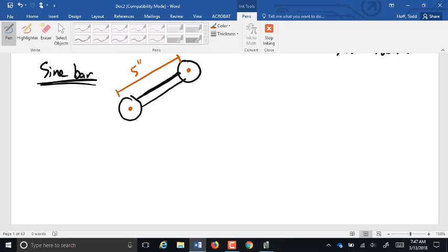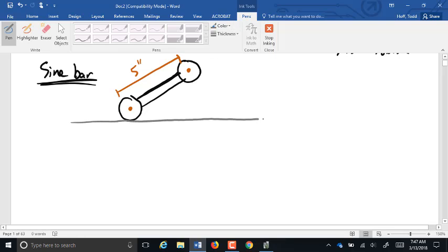In industry, usually they're 10 inches to make them a little bit longer, but they do have 5-inch ones. And because they're very, very precise, I mean, we're talking to within a 10,000th of an inch of that dimension from center to center, we can use them to create very precise angles. So if this is sitting on a surface here, now that again is not just any table, it's either a precision surface like a stone, or it's a table for one of the machines or whatever.